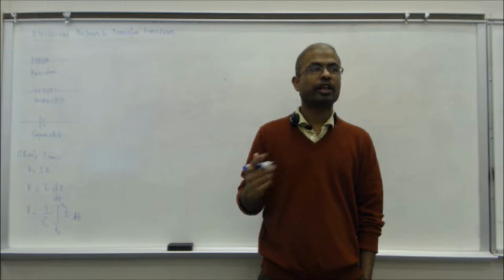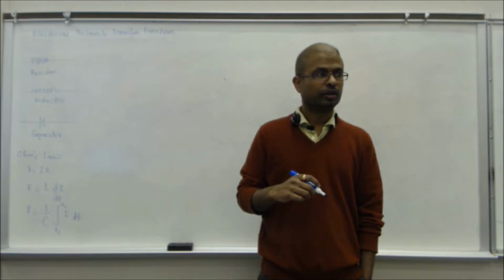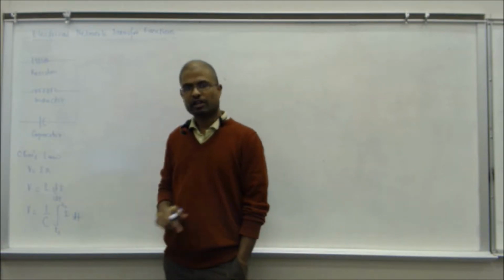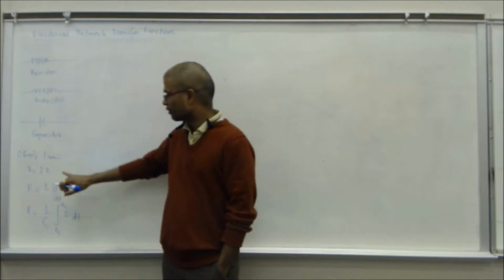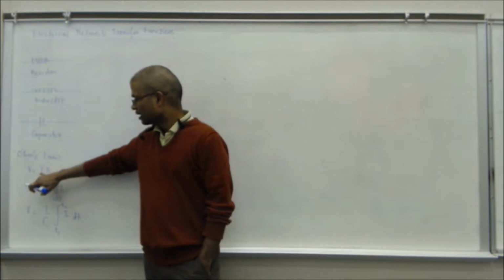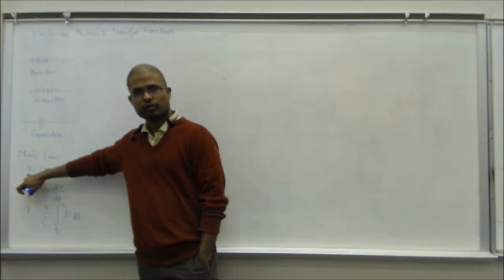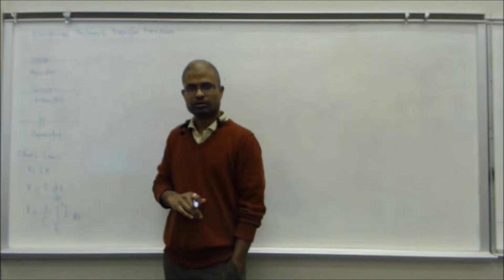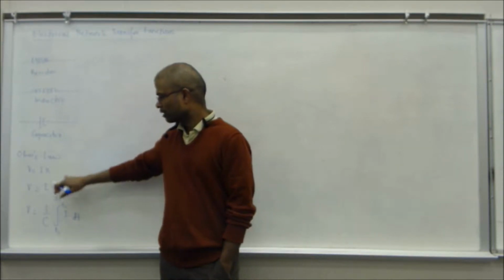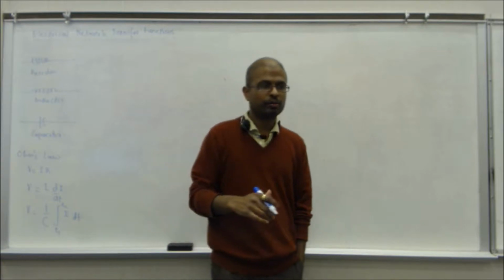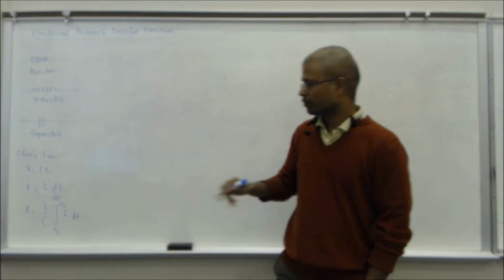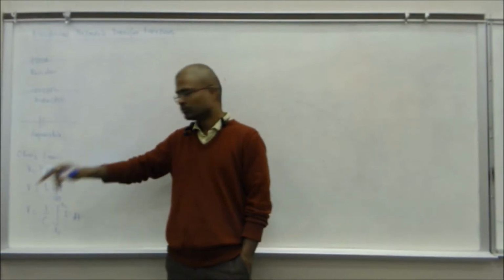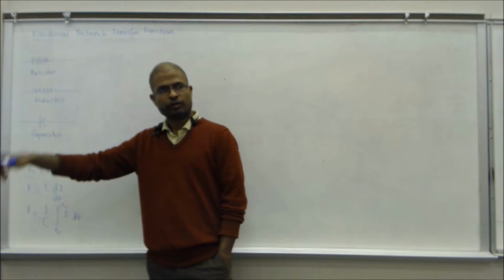When current starts flowing, it heats up that particular element because there is activity, and when it heats up, this resistance slightly varies. Okay. So if resistance varies, what happens? Voltage is the same. Voltage you are not changing. So the current flow reduces a little. But the reason why we allow the system to heat up is we say it will stabilize. So we know the resistance will heat up only to a particular value, and then there is almost a constant current flowing through the system.